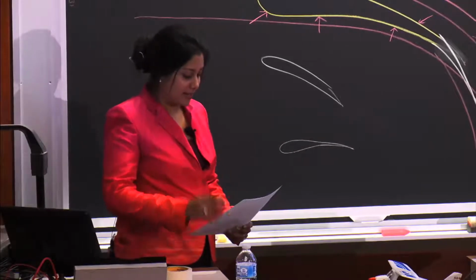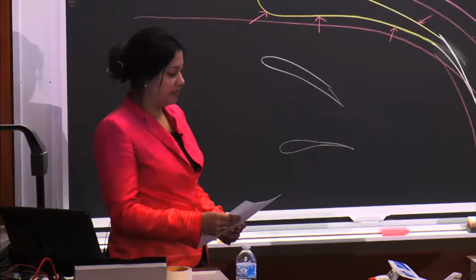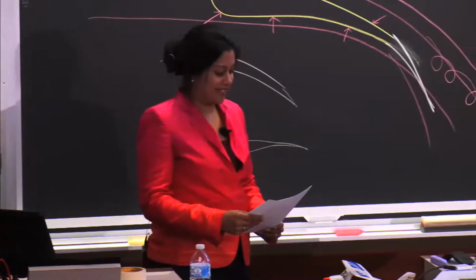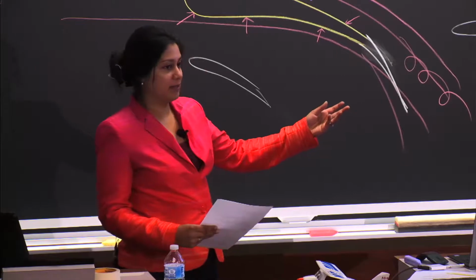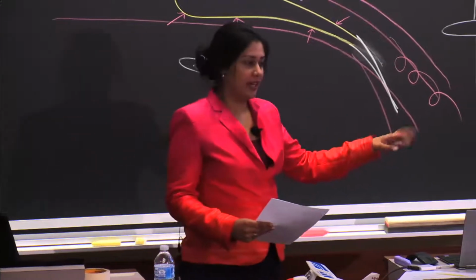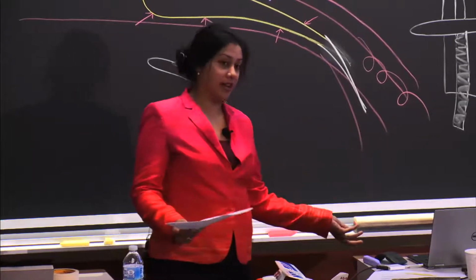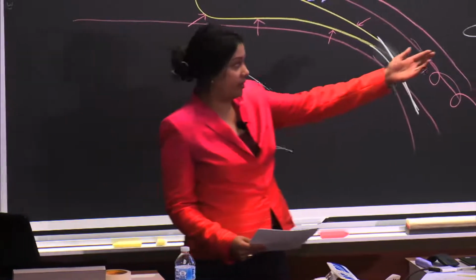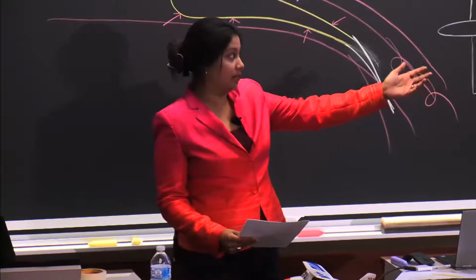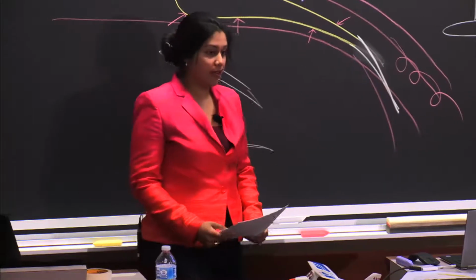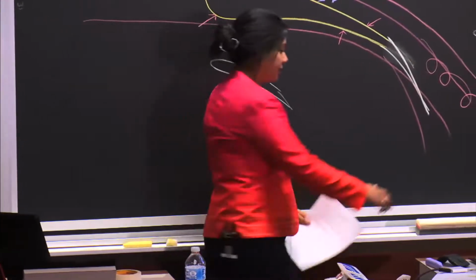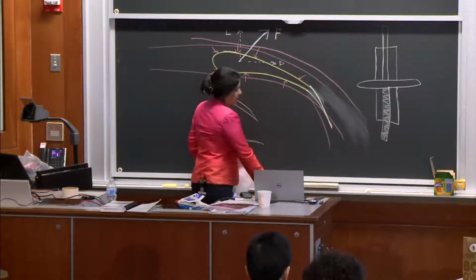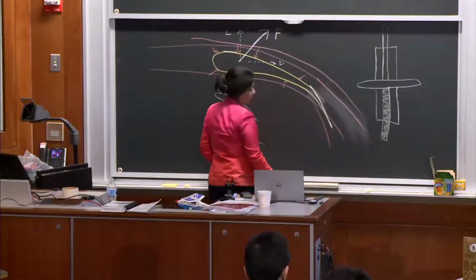And so instead, we basically assume that that doesn't happen. We impose some limitations or conditions on the airflow, which are not actually true, but help us with approximating lift. One of those is the Kutta condition that you see at the bottom left, which is this smooth flow off. Basically you say that none of this turbulence is happening, and the air moves very cleanly off.